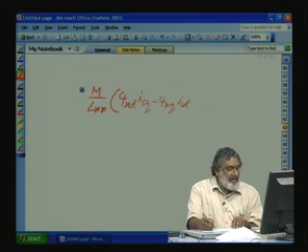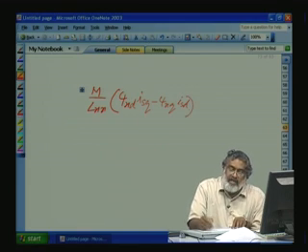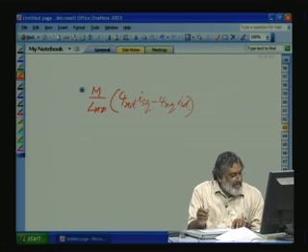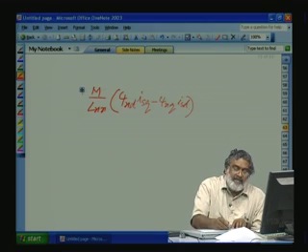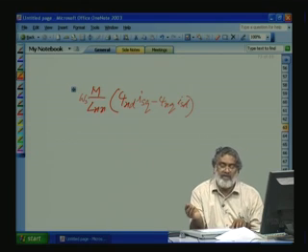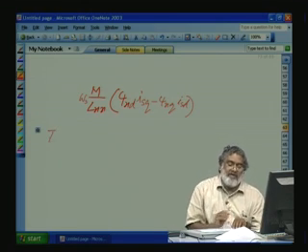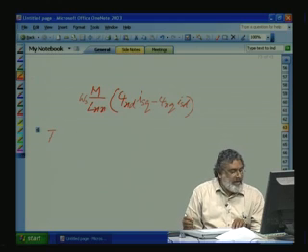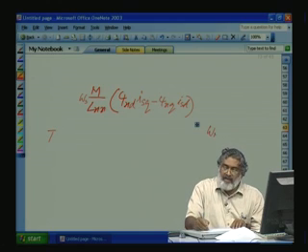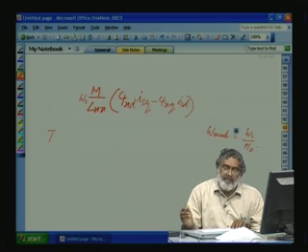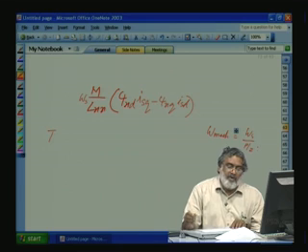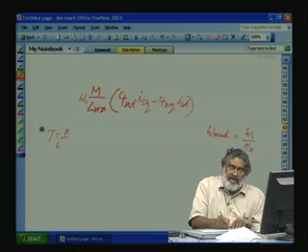This way the final equation will come. But if you see here, this has to be multiplied by omega s. Now for the torque, you have to divide by the mechanical speed. Omega mechanical is equal to omega s divided by P by 2. So T is equal to P by omega mechanical.